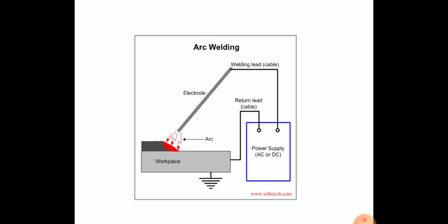The arc welding principle is that an arc is generated between the positive pole of DC, direct current, called the anode, and the negative pole of DC, called the cathode. When these two poles are brought together and separated by a small distance, 1.5 to 3 mm, such that the current continues to flow through a path of ionized particles called plasma, an electric arc is formed. Since the resistance of this ionized gas column is high, more ions will flow from anode to cathode. Heat is generated as the ions strike the cathode.